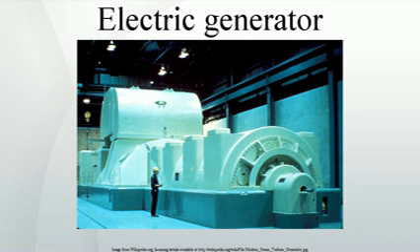Induction generator. An induction generator or asynchronous generator is a type of AC electrical generator that uses the principles of induction motors to produce power. Induction generators operate by mechanically turning their rotor faster than the synchronous speed, giving negative slip. A regular AC asynchronous motor usually can be used as a generator, without any internal modifications.